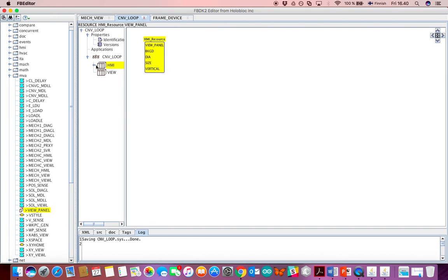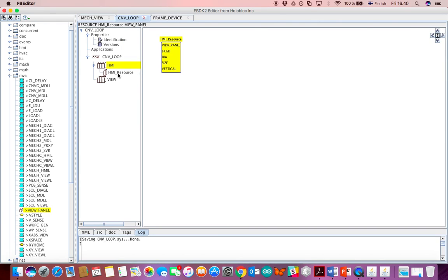And as I have added it and named it, you see that I can further extend this tree of a system and see the HMI resource appearing in the tree. And as I select it, we see this default block added on each resource, having cold, warm, stop, event inputs for our resource. There are outputs, of course, for this e-restart block, but we will use these events to initiate a different function block at the corresponding resources.